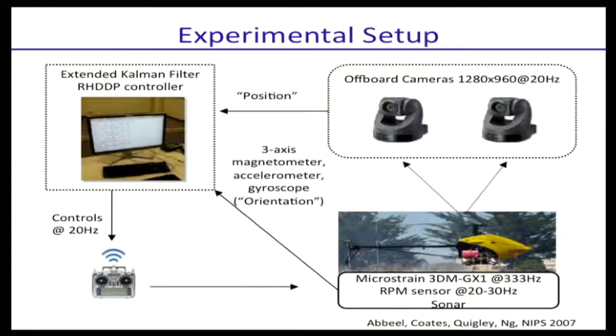Once you do that and you set up a computer and the code so that this runs super fast and doesn't get interrupted by any operating system calls and things like that, then you can actually get this to work at 20 hertz, including the Kalman filter at 100 hertz, control at 20 hertz. Control at 20 hertz also means that you actually don't use the full 1/20th of a second to do control. You use about half of that, 1/40th of a second, because latency is also bad. It's not great to compute an optimal control, but 1/20th of a second later only. You want to be quick, based on the current state estimate, to get out what you think is the right thing to do.